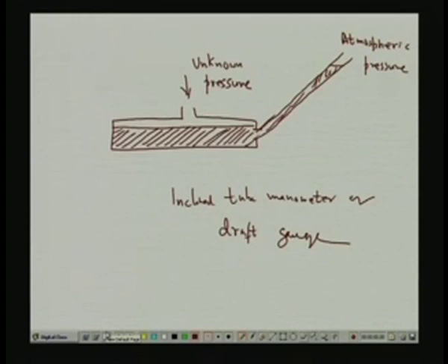Now, all these manometers, as you know, are basically indicating instruments, as I told you earlier. So, we won't get any electrical output this time. This is basically a monitoring instrument, neither a transmitting instrument nor a recording instrument. Though people tried with the mercury in glass manometer with some electrical output. How? Let us look at it. People tried like this one. You see what they did.